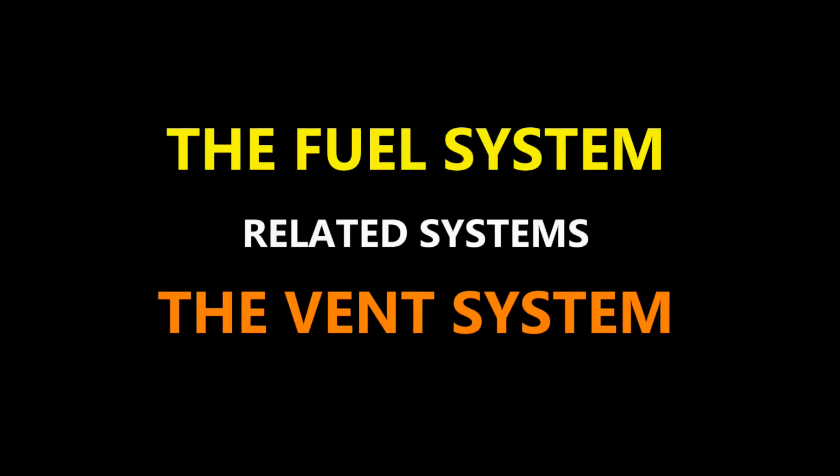Okay, that was the quantity indicating system, and now I want to look at the vent system, because remember I said there has to be a way for it to be exposed to atmospheric air. So what we're going to look at here are these vent tanks. We want an equalization of pressure that's constantly going on, because you don't want a buildup of pressure inside the tanks.